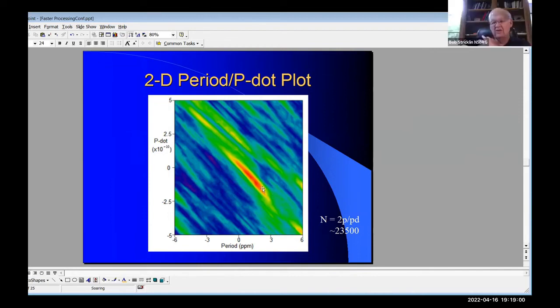And I wondered, have you looked at adding a couple more antennas and looking at polarization? Yeah, I did. I can look at polarization. I built my antenna so that I can turn it round by 90 degrees, and I have tried horizontal polarization, vertical polarization, one way, the other way, and I get similar results whatever I do. But I haven't tried doing pulse analysis. My research has really been to find out how low a signal to noise ratio measurement I can recognize.